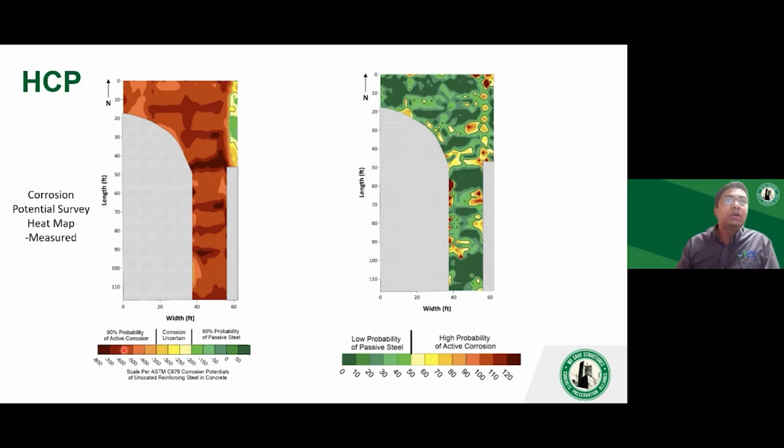You need to use delta measurements. You just take a difference between two adjoining locations, because a difference between two adjoining locations is the driving factor that drives the corrosion. The higher the difference between two adjoining locations, the more is the susceptibility towards corrosion. For instance, if the potential difference between two adjoining locations is 100 millivolts, it's almost certain that the corrosion will happen in the near future because you're forming small macro cells in these areas.